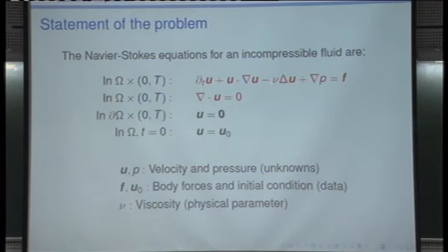Okay, it's the only physical parameter that intervenes in the problem because the density is dividing everything. In fact, the original equations, when you derive them from the conservation equations of continuum mechanics, have a density here, the so-called dynamic viscosity mu here, and here a density. And the pressure is not that pressure, but the pressure divided by the density. Okay, this is sometimes called kinematic pressure. So those are the equations, beautiful equations that we have to solve.